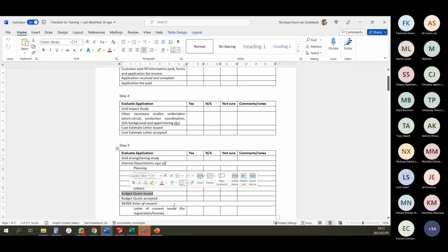I mean, obviously on the developer side, they need to have their own SCADA capabilities, but on the utility side, making provision for SCADA. Isn't the SCADA capabilities and the control only checked later on with the grid code compliance? Yes, but if you need anything on the distributor side, you need to check it now. It will at least be aware of it. That needs to be included in your budget, your quotes there.